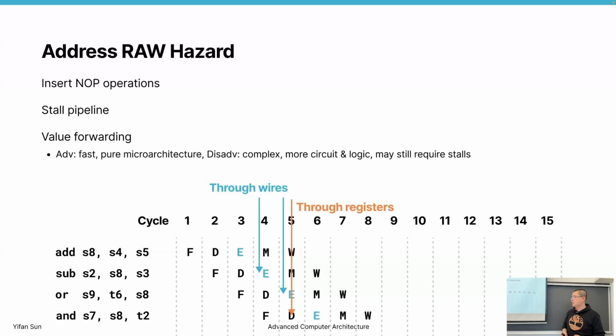Then in that case, you need to find a way to really use the die size budget and the energy budget, to convert the improved energy and die size budget to higher performance. So how can we do that? Definitely one way is to add more cores. But can we make the single core faster? Because in many cases, you cannot really rely on multiple cores.